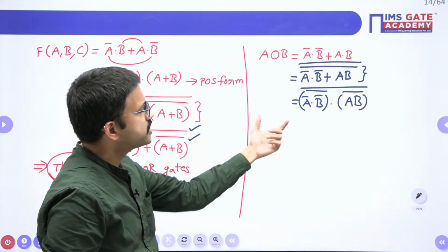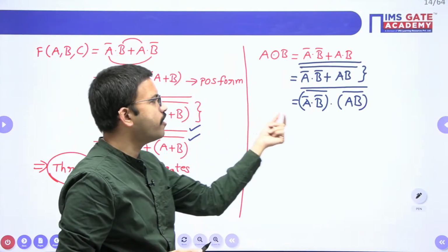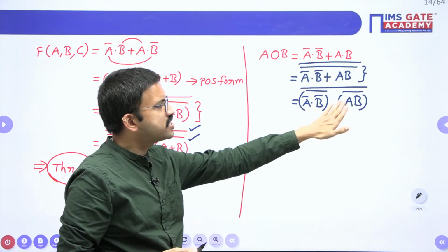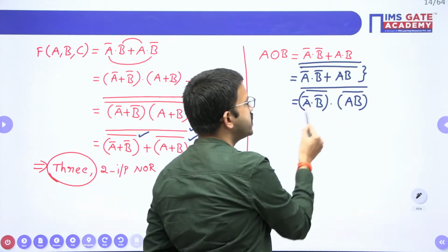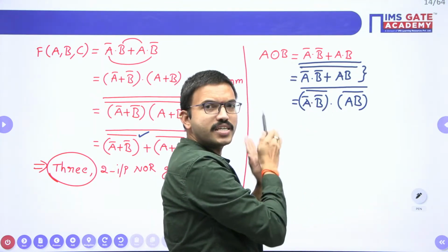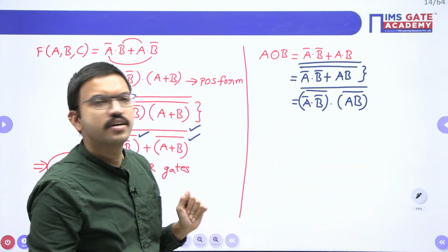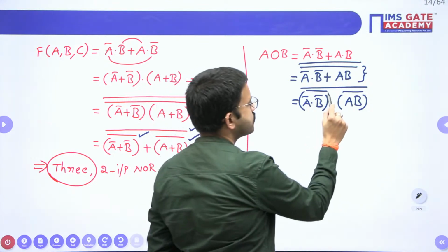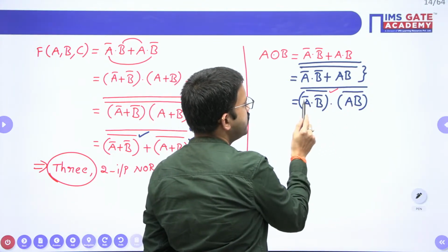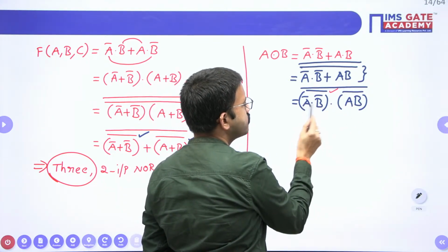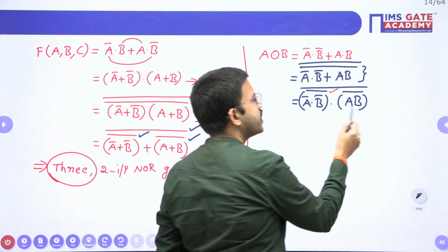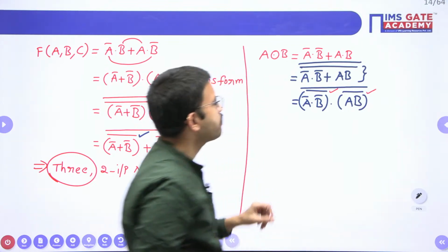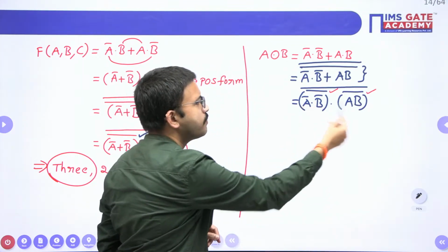Now just look at this expression. In the question, if they have mentioned that the variables in their normal form and their complement forms are available, in that case, you don't need to generate A bar, you don't need to generate B bar, because it is directly available, right? Yeah, Saptak, you can cross check here. See, here it is like x1, x2. When you are having x1, x2 whole bar, you require a 2-input NAND gate. Similarly, for A B bar, you require a 2-input NAND gate. Now you assume this is y1, this is y2.